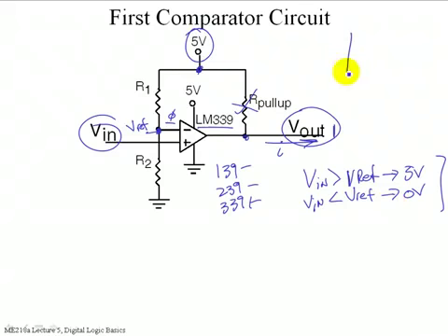What I found was that when the device was activated, bang, it'd snap right down to 0 volts and read a nice clean 0. And then when it was supposed to turn off, it would meander around, and then it would turn back on and snap down to 0. But without that pull-up resistor, there's not going to be any consistent voltage that appears on that pin. And you're going to pull your hair out trying to figure out, why is this not going where it belongs? Okay? So, pull-up resistor, absolutely required if you want to actually have a high voltage on that output. So what